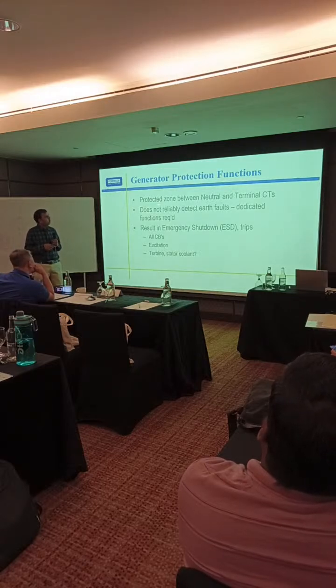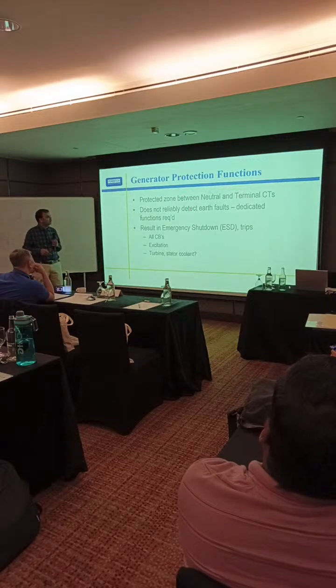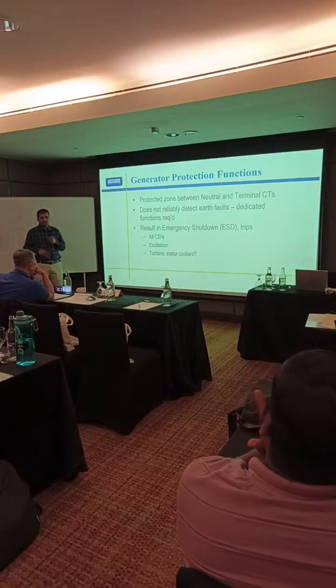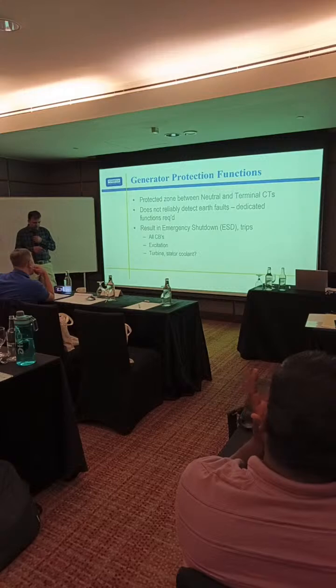So if the differential relay is operating, then what condition will there be? All CBs will be tripped: excitation, turbine, stator, everything, because differential is the main protection.